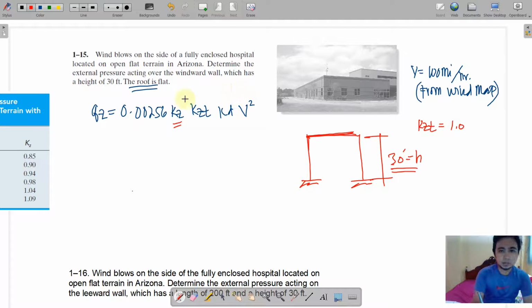So next, how about the value of kd? So kd here, we are just concerned with the wind load. Although this is a directional factor, we will just consider here kd is equal to 1 because wind load here is not combined with any other loading as the problem is silent about it, but we are just concerned with the wind pressure acting externally.